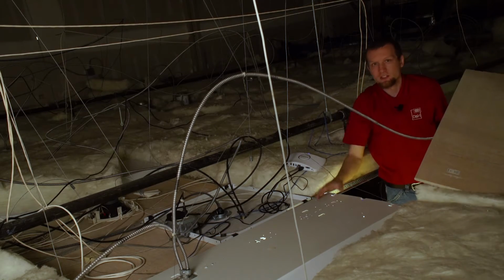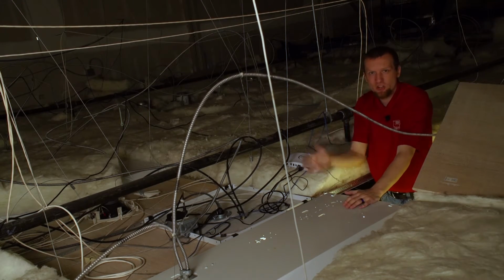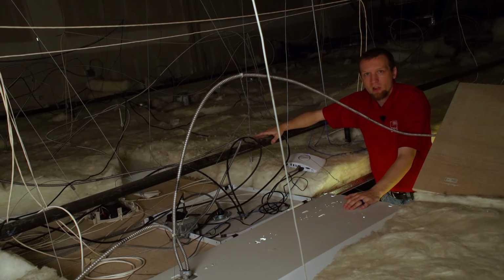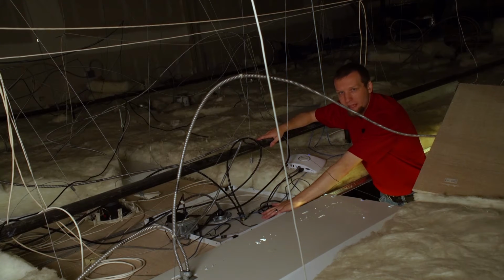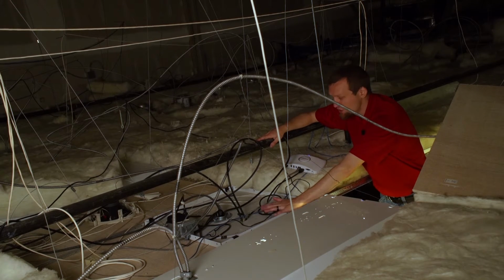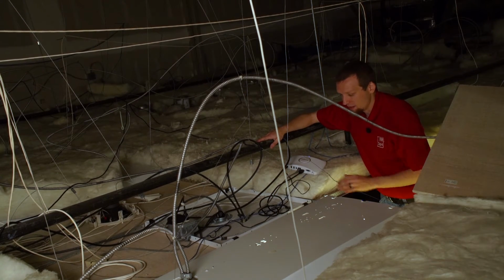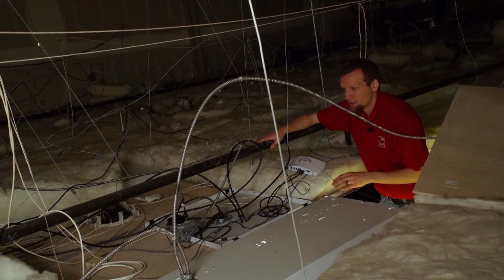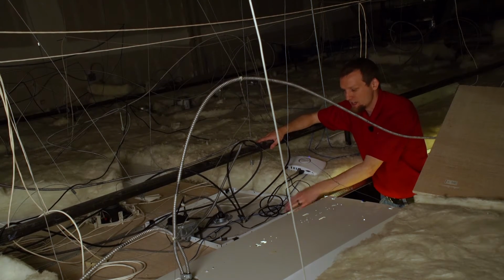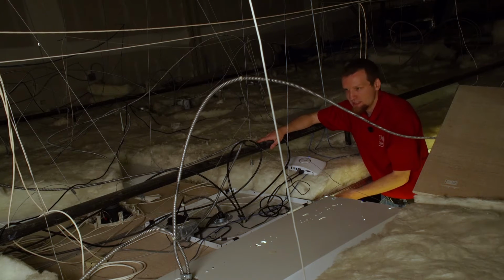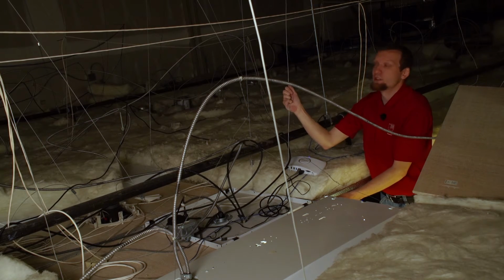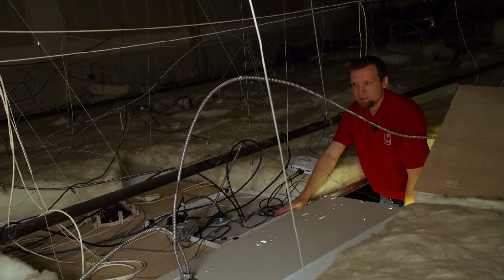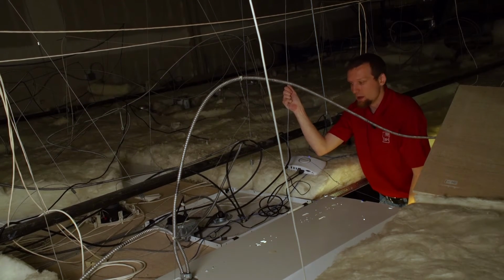Hey everyone. So here we are above our conference room, and I wanted to show you what it looks like above here once we've got everything installed. To start with, here's the actual plate that we use to mount the universal projector mount to the drop ceiling. It is a plate that literally just sits right on top of the panels themselves. The plate screws into the steel guides that are up here and are tied down as anchored to the ceiling by these guide cables. So in case the drop ceiling gives out, they've got an extra anchor as well.